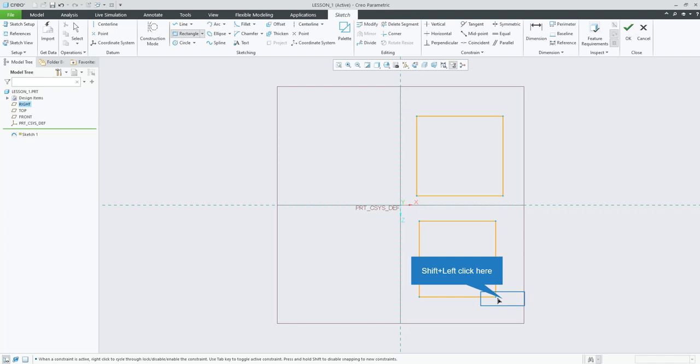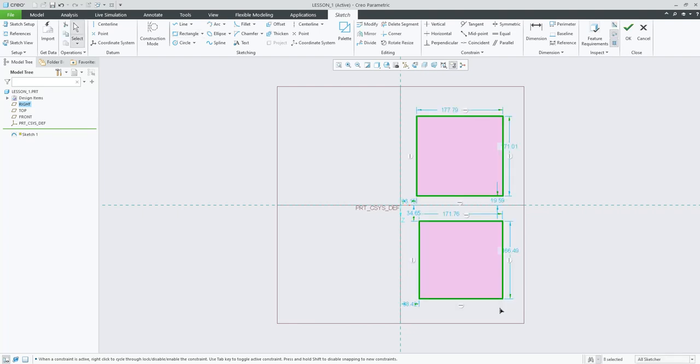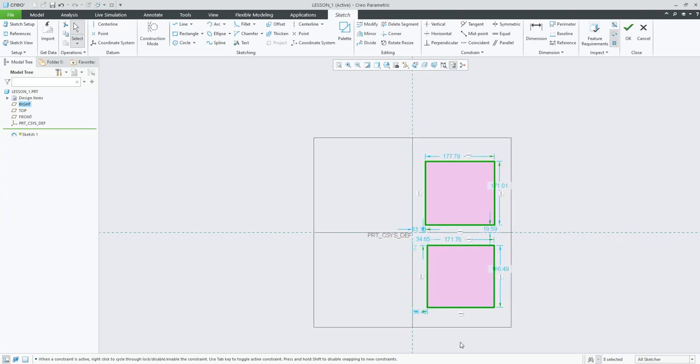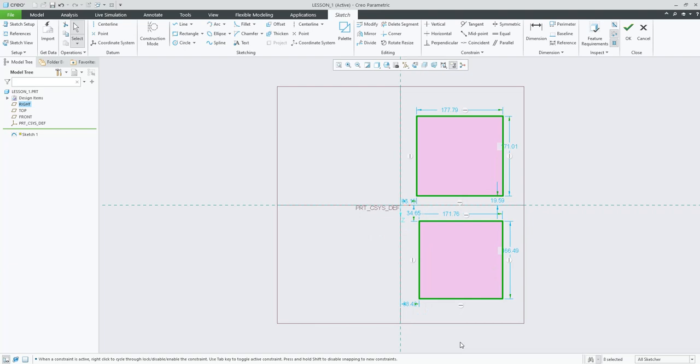It can default to that. If you don't want it to default to that, before you click, hold Shift, then click. It will not have any references to any other parts. It will not have any constraints that match other parts. So then you can center mouse, and center mouse will close the function.